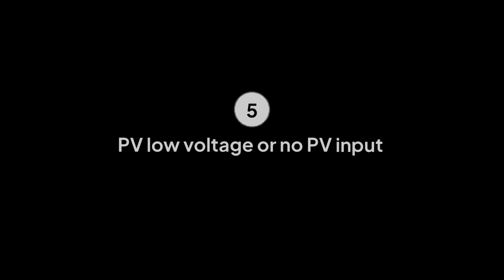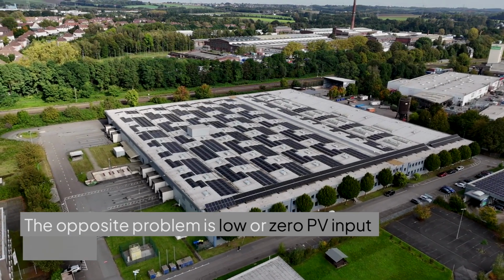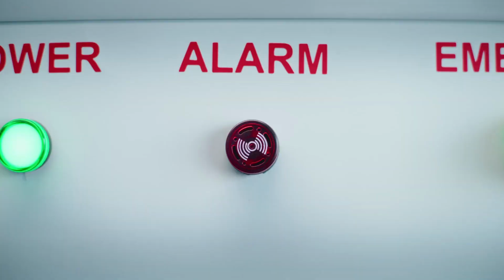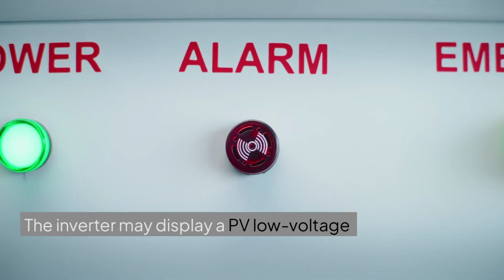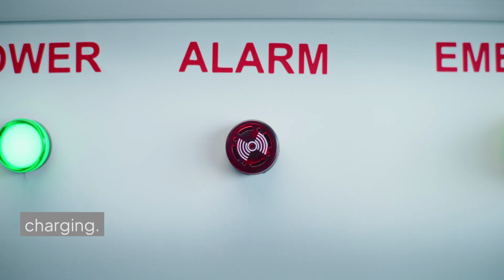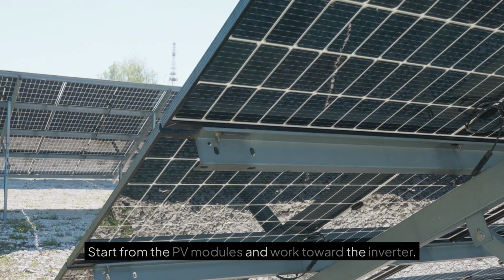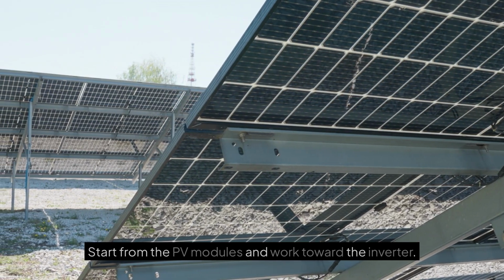5. PV low voltage or no PV input. The opposite problem is low or zero PV input voltage. The inverter may display a PV low voltage alarm or simply refuse to start solar charging. What should you check? Start from the PV modules and work toward the inverter.